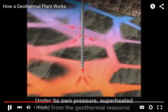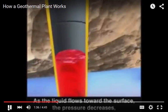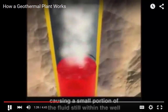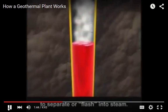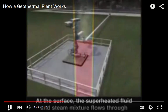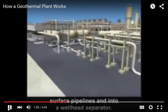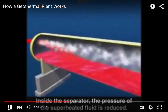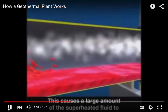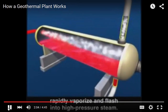Under its own pressure, superheated fluid from the geothermal resource flows naturally to the surface through production wells. As the liquid flows toward the surface, the pressure decreases, causing a small portion of the fluid still within the well to separate or flash into steam. At the surface, the superheated fluid and steam mixture flows through surface pipelines and into a wellhead separator. Inside the separator, the pressure of the superheated fluid is reduced. This causes a large amount of the superheated fluid to rapidly vaporize and flash into high-pressure steam.